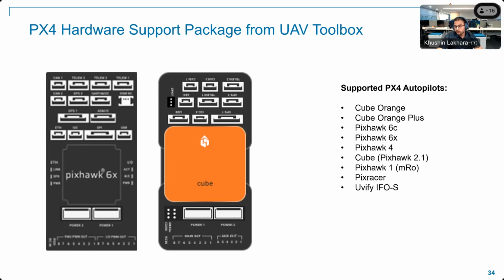Now we'll move forward and discuss various other sections on how you can perform the HITL simulation and how it works. But these are a few of the hardwares supported by the PX4 hardware support package for UAV toolbox. If you are going to use any of these hardwares, you can directly generate the optimized flight controller code and deploy it on your hardware. But if you're using any other flight controller hardware, please feel free to reach out to us and we will help you generate custom code for those other flight control hardwares as well.